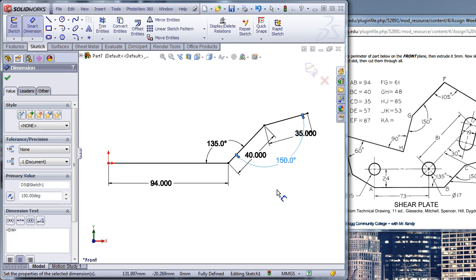This drawing gets really confusing. The dimensions are on top of each other. It's a mess, but you should be able to pull it off. Again, do the outside perimeter, extrude it, then start a new sketch. Draw the 2 circles. There's a vertical relation between this corner and the center point. These are horizontal. This line, relate it parallel to this edge of the part. Then you can draw this center line, put the 30 in there, draw a couple circles, put your 19 across.